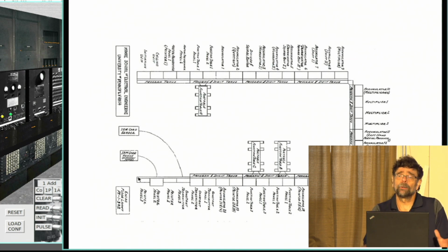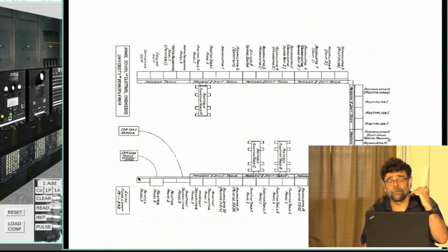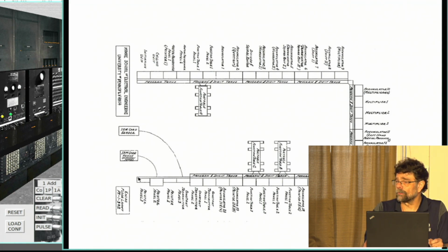They got a lot of pushback from all of the experts who said there's no way it's going to ever run because there's going to be a tube burning out so fast you're never going to get a computation done. This isn't to talk about the hardware engineering of it, but I'll just tell you quickly that basically they figured out ways of operating the tubes in such a way that they would tend to last longer, with a slightly lower filament voltage than they were rated for.